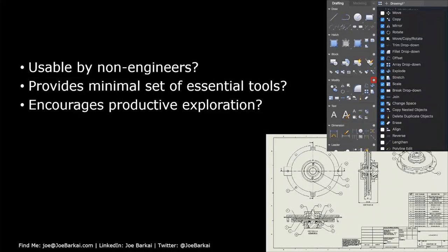And this is actually, interestingly enough, a hot topic today, because many organizations move from traditional manufacturing processes and methods to additive manufacturing, to 3D printing. Issues around material distribution and wall thickness and removal of support structure become more complex issues. So it would be nice if we had a tool that allows manufacturing engineers to do a very basic analysis of material distribution. Another area in manufacturing would be calculating draft angles for injection molding and forecasting. Again, you don't need a full CAD package for it, but you do need to know those attributes in order to design the process properly.